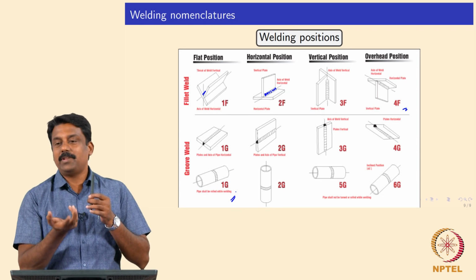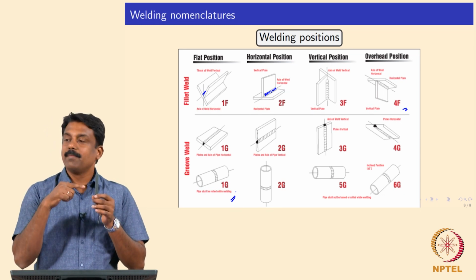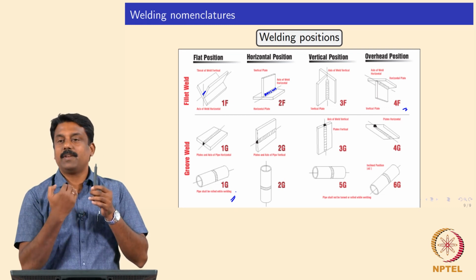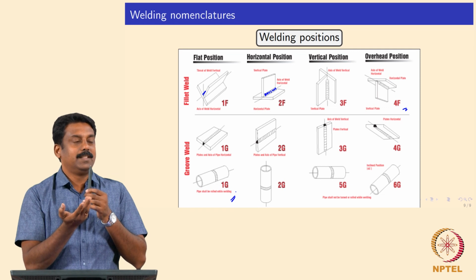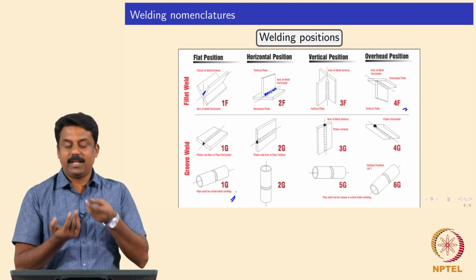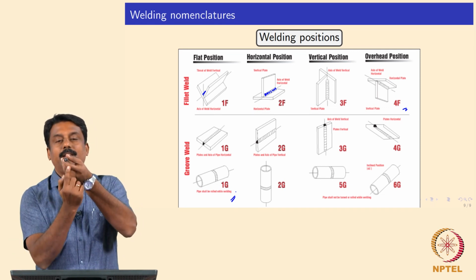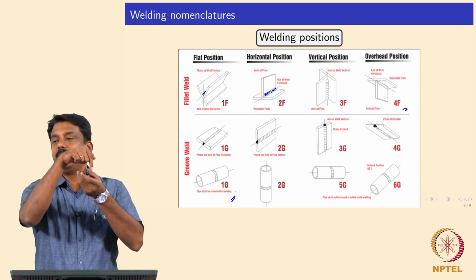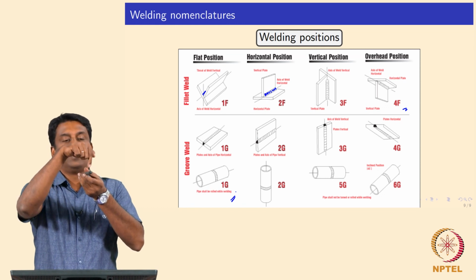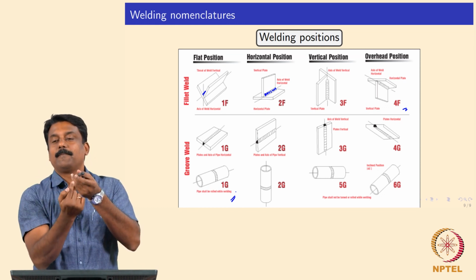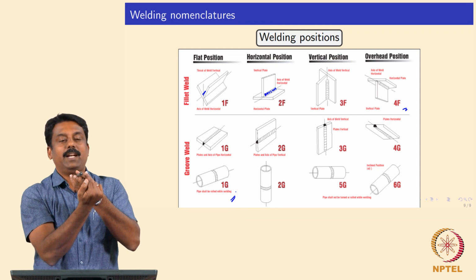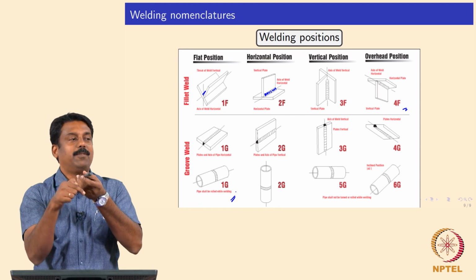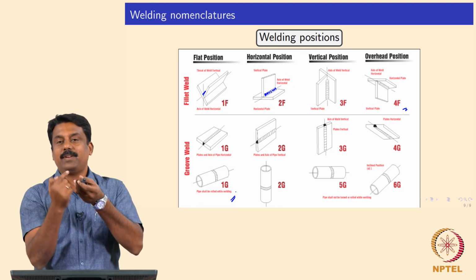So that welding is very challenging because in a single welding operation, you also change the metal transfer characteristics, isn't it? So gravity changes. You keep it like this, the pipe is there, and then you start from here. Generally we start from here because that's easy. Gravity assists metal transfer. But when you go around, the entire metal transfer characteristic can change. So remember, what are the forces that assist the transfer?